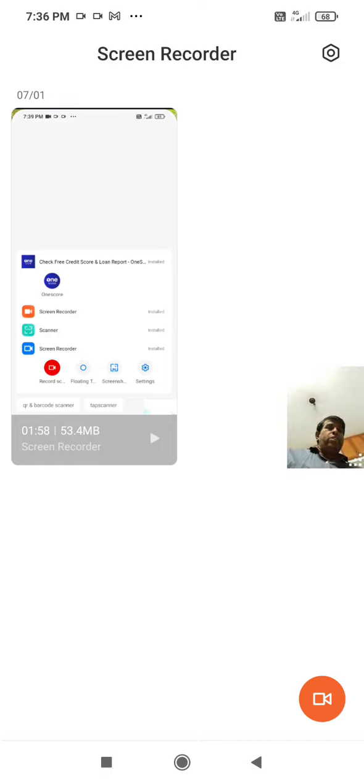These are the defects: bar, bark, bias filling, board filling, broken end, chaff, coarse end, color run, end out, fine end, flat, float, fly, fuzz balls, fuzz, hard size, hitchback, jerked in filling, kink, mispick, misread, mixed yarn, pick out mark, read mark, shaded, shuttle mark, slub, smash, temple marks, tentering marks, uneven finish, wrong draw.